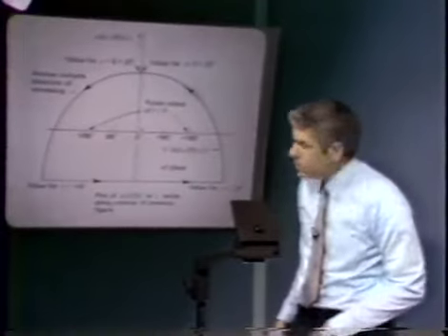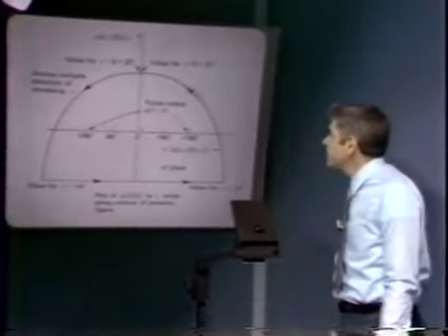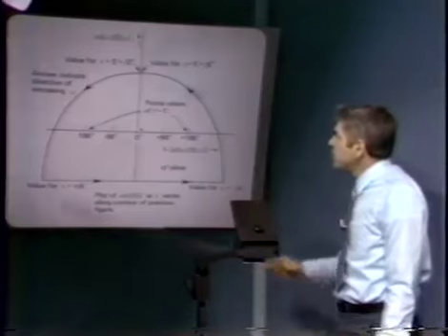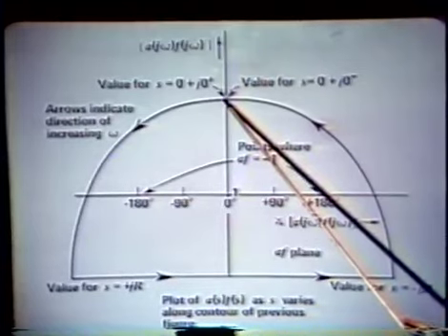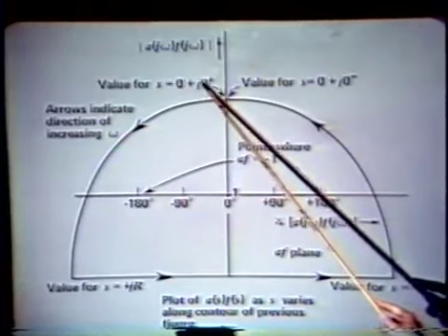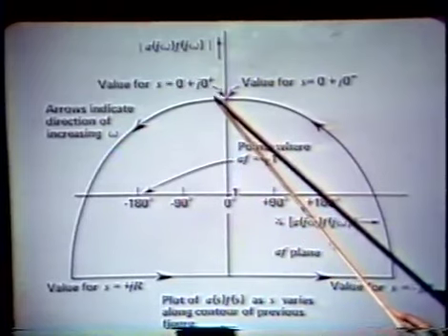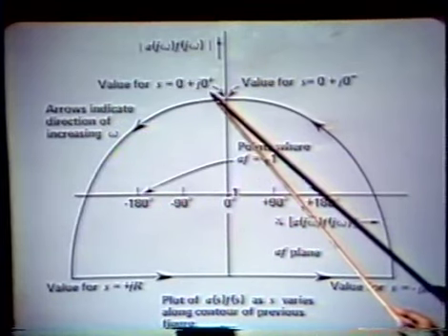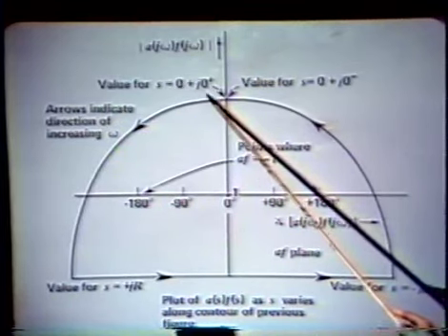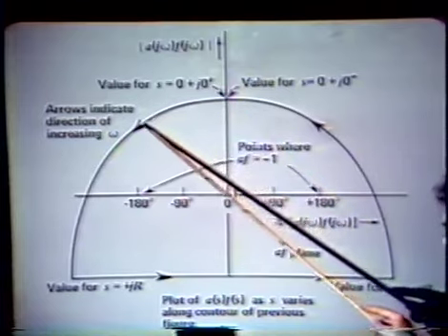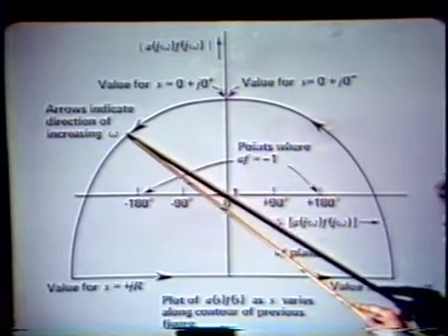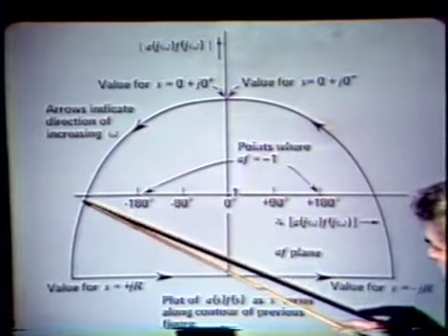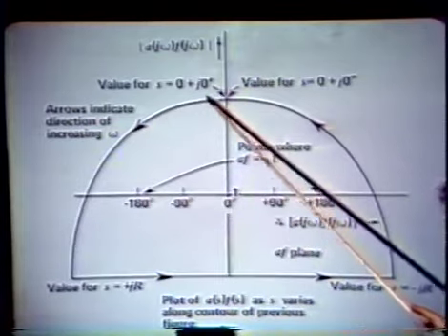And when we do that, we get some contour in the AF plane. And I've assumed this is the one that we've gotten. Here's the value of the AF product for s equals 0 plus j0 plus. As we increase omega, let s equals 0 plus j omega, and only an imaginary component, the real component being 0. We assume, for this particular illustration, that the curve follows this path. In other words, its magnitude gets smaller.